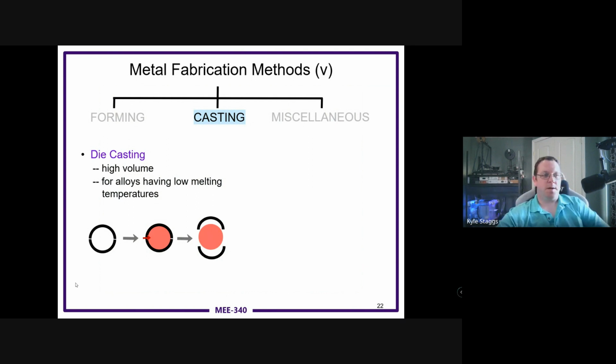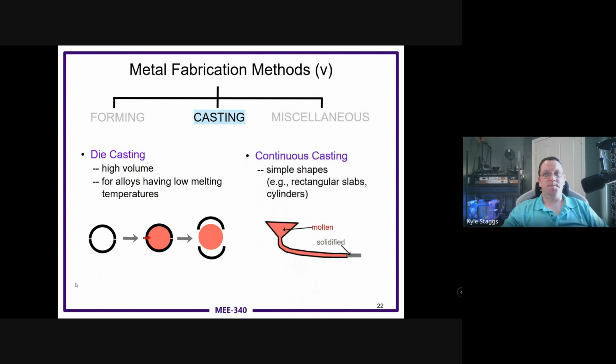A lot of extra material, a lot of materials that have to be melted back down and recaptured later. That creates a lot more workflow for the process here. So the low melting temperatures are really important for this process, because that way they don't have to make the dies out of something like sand that can carry the high temperatures. So that's why something like plaster of Paris is useful for that sort of lost wax type. But you can also use ceramic molds and develop them in that same way.